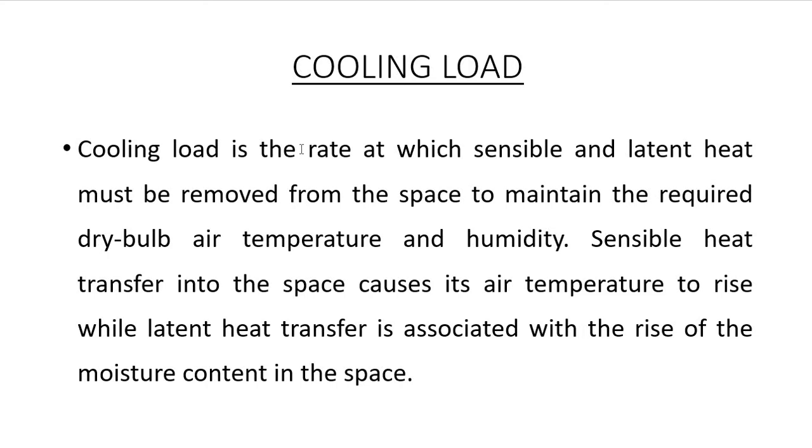Cooling load is the rate at which sensible and latent heat must be removed from the space to maintain the required dry bulb air temperature and humidity. Since we have to control the temperature as well as humidity, if you want to reduce the temperature, you have to absorb heat from that space. If you want to reduce humidity, we have to remove moisture from that space.